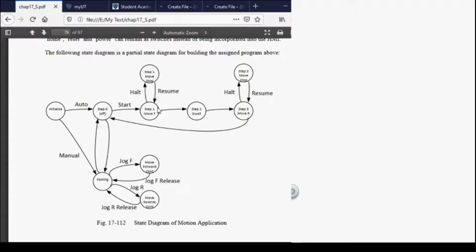And that's why it's very important that I use absolute control, because let's say I stop at 150. All I have to do is say go to position 200, let's say, or maybe 400 if I'm going 2 revolutions, and it would finish that revolution off. It wouldn't have to know where I'm at and then calculate for me. It just says go to that finished position, and then it would move to here, and it would move to here.